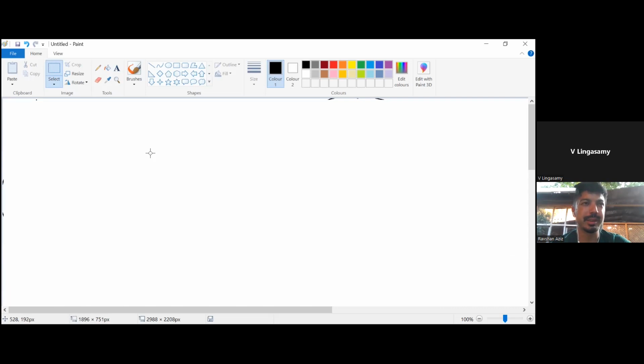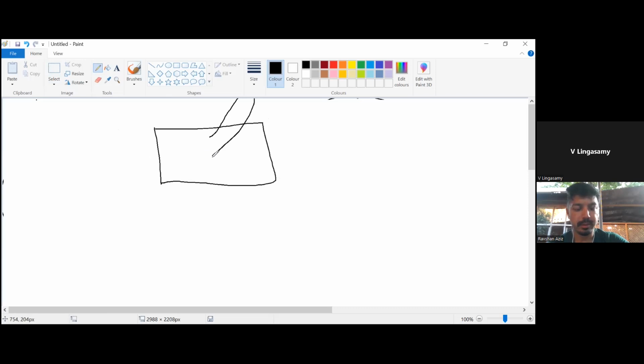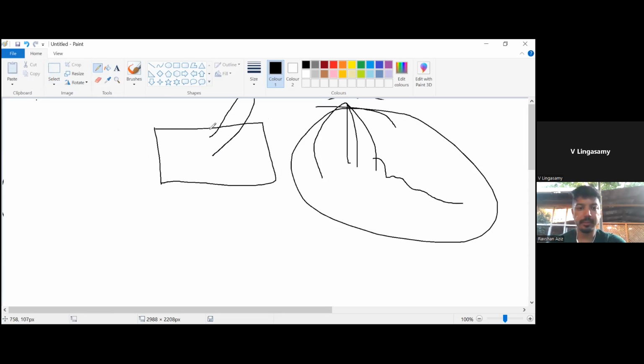That can definitely be done. You might have studied phased arrays, right? By applying the appropriate excitation, you can control the beam. You can broaden the beam, narrow the beam, or control the side lobe level. Indirectly, you are controlling the excitation in terms of amplitude and phase. Similarly here, when the phase distribution gets changed, your radiation pattern behavior is going to change. The beam will change.